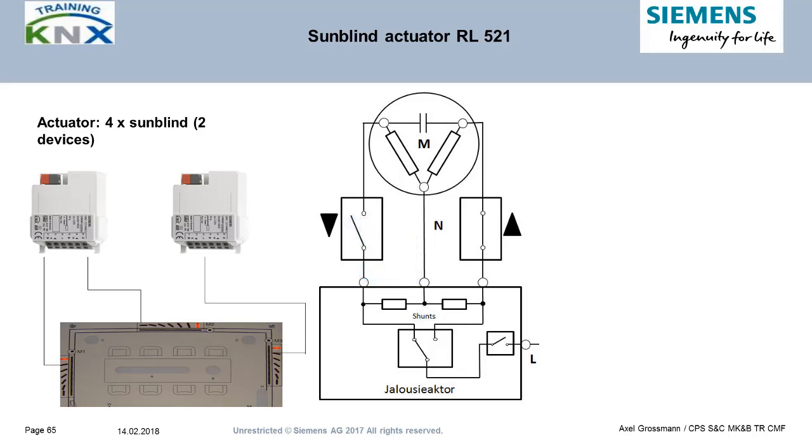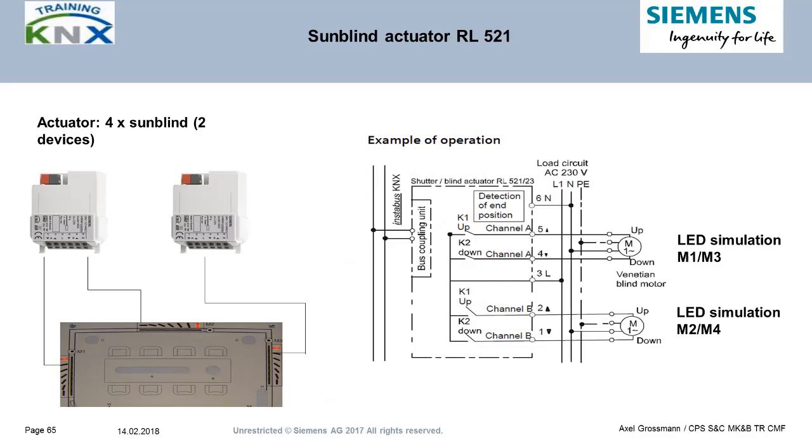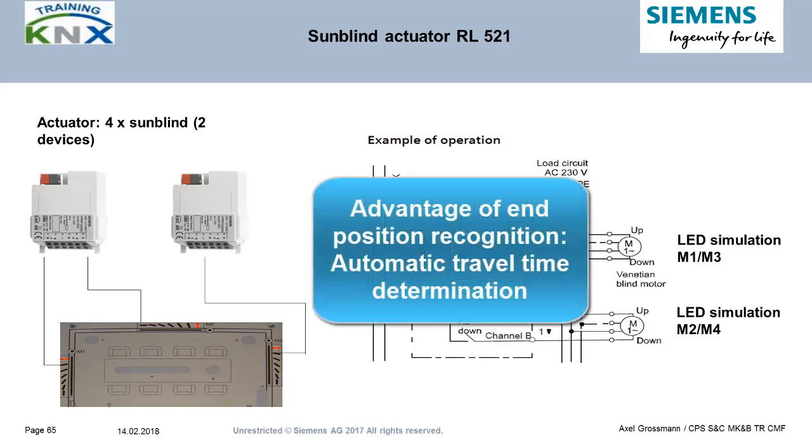As soon as such a contact opens forcedly, the loopback voltage is also interrupted. The detection circuit of the actuator also will switch off the relay. Moreover, the true travel time is being measured through this, so the integrator doesn't have to care about precise spinning timers parameterization. More details about this also in the advanced KNX training.